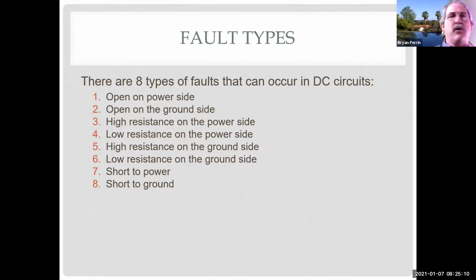But if that ground is shorted to power, now what? We're blowing a fuse. We're melting things. That's a problem. If I have a power side switch system, and that power side is shorted to power, maybe it acts like a bad switch because it's got power to the load all the time.